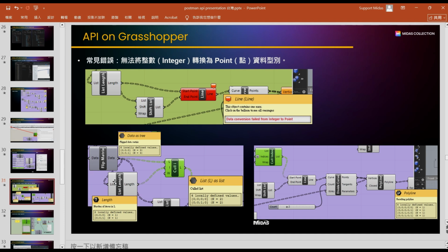So that's why if you have the list length, you need to call the list length first and then have the other data that is the actual data. So this actual data is maybe 3 coordinates, and you have a list length of number 3. So it means that the call index output will be only 2 coordinates. That's why the 2 coordinates can be indicated as a start point, and the shift list, that is the first coordinates plus 1, can be attributed as the endpoint.